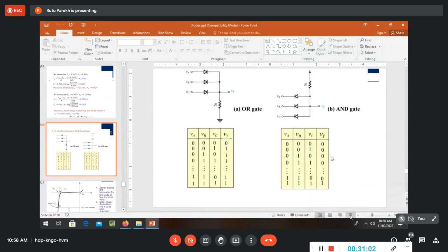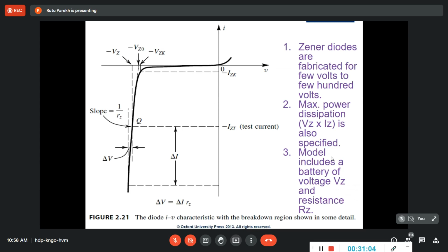Anyway, without wasting further time, I have talked about this. What is basically a Zener and how it is different, all the physics and everything I have taught. I gave you an example also that this is basically to protect your circuit from fluctuations. When there is a fluctuation in the voltage, the current will change drastically, and this current may damage your device because these devices have a limited range that they can withstand. Maybe it can bear some maximum current or power.